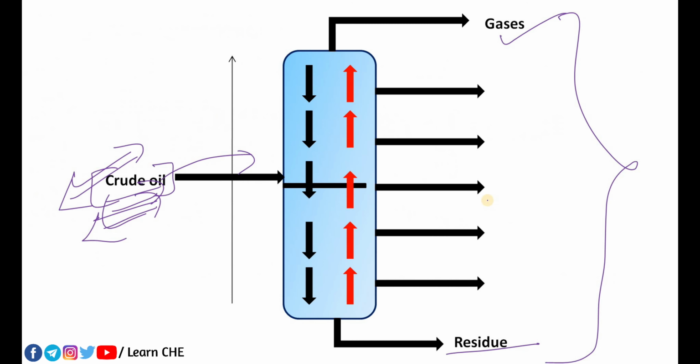The example is, this is our diagram. In this diagram vapors go upward, and after that they go into the condenser. After the condenser some amount of the liquid mixture goes into the first tray of the distillation column, and the remaining part is collected in the accumulator. Suppose this is an accumulator. So this liquid mixture is known as the reflux.